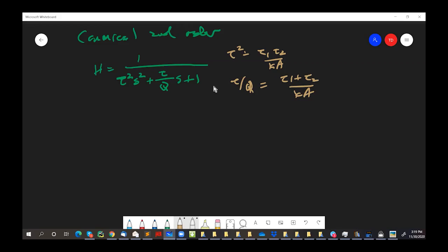This is quite abstract right now. The reason is I want you to think about this expression on the left here in terms of this Q. So tau is going to be somehow a time, right? Because it's multiplied by the frequency. So time times frequency is dimensionless on the left here. So tau is some kind of generic time constant. Q is some measure of how important this middle term is. So what happens if Q is really, really big?